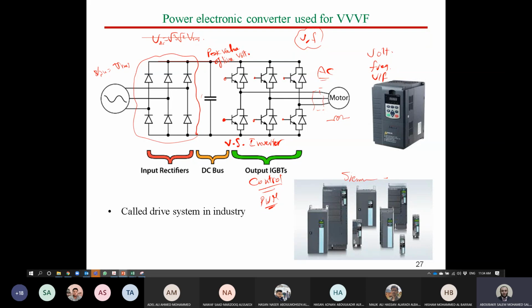However, besides the PWM control, the waveform here will not be sinusoidal. It will also include a few harmonics. In order to remove all harmonics, you have to add a filter. But this is if you have a critical load that is not allowed to be supplied with any harmonics. But in the case of machines, in the case of motors, you don't need to add this filter.